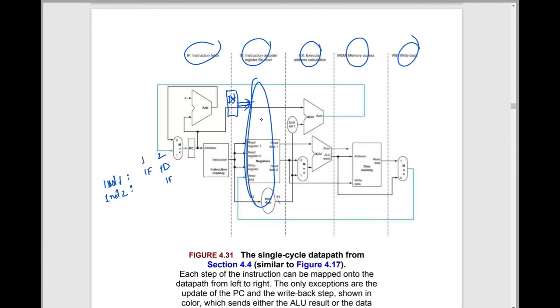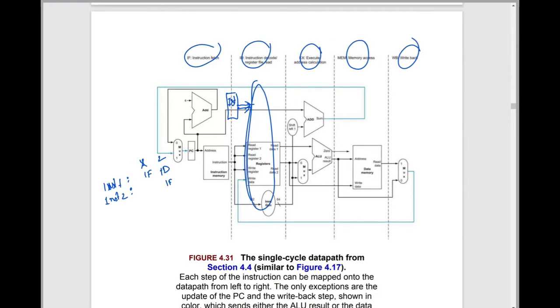So in the pipeline, in every stage, in every module, suppose at cycle x, any module is performing some operation, then at the end of this cycle, this result will be written in a temporary location here. This is called a pipeline register. The result will be written in a pipeline register, such that in the next cycle, when this module starts working on a new instruction, the old data stored here will be used by the next module. Otherwise you cannot communicate between these stages.